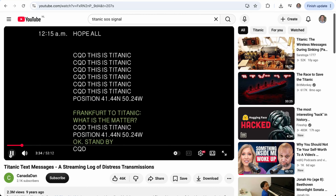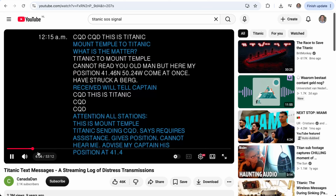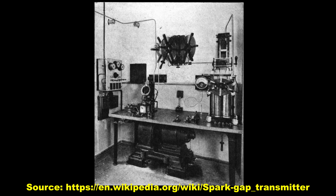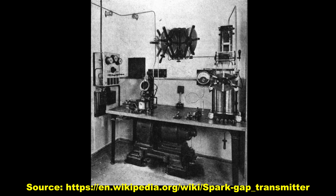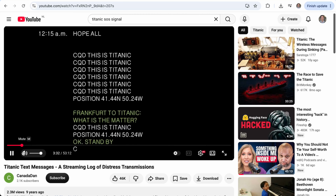As we can see, this video was published 9 years ago and it has more than 2 million views. But the interesting thing is that these signals are incorrect. Why? The reason is simple. The Titanic was built in 1911, and at this time vacuum tube transmitters were not in use yet. So the Titanic was using a spark gap high voltage transmitter made by the Marconi company. There were no vacuum tubes and no transistors at that time. That's why this video is incorrect, and the Morse code signal was not sounding like this.